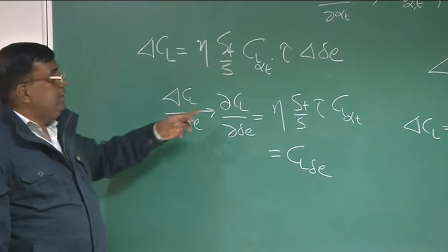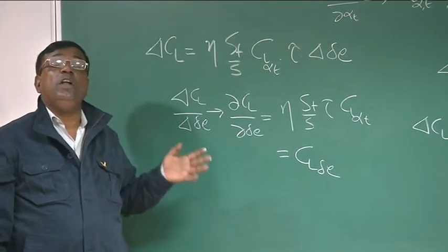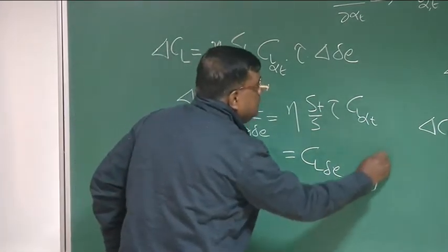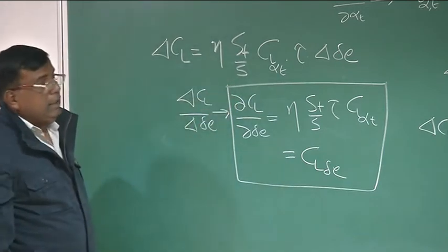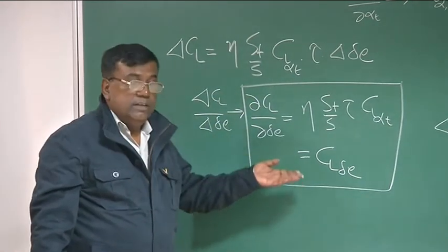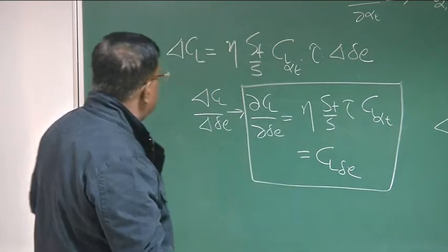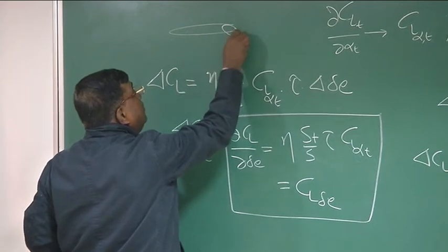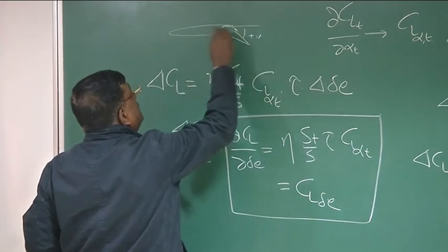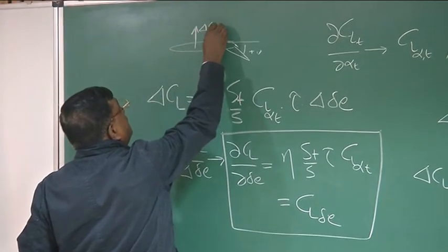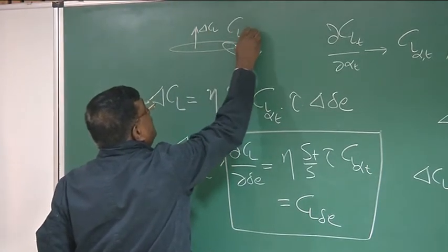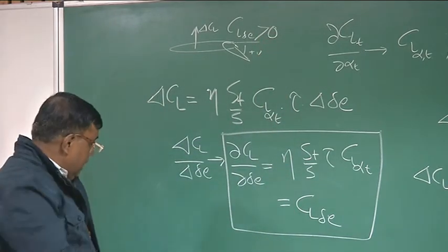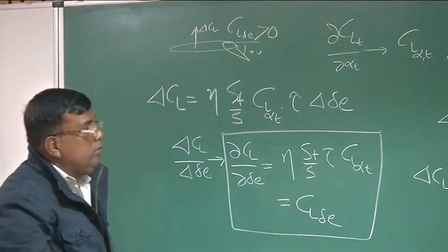Okay? So what is this CL? This CL is of the whole airplane. This is very, very important, and you should understand this. And we know that we can easily calculate this. And by sign convention also, you know, if I put delta E down, which is positive, there is an additional delta CL here. So CL delta E is, sign wise, greater than 0. Clear? Okay. Once CL delta E is clear, we will now go to CM delta E.